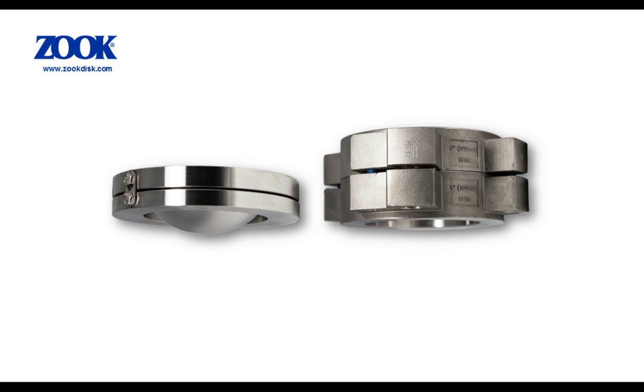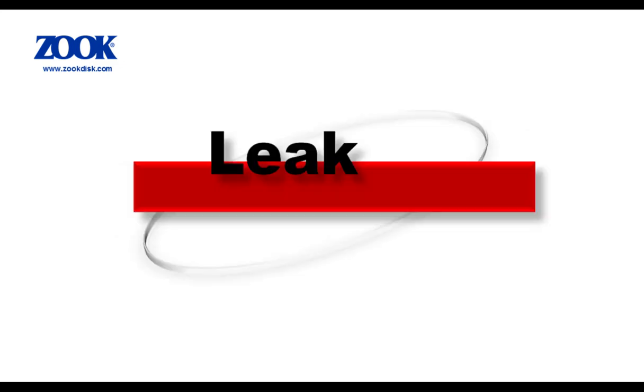What it turned out was that in order to reduce cost, similar to the assembly on the left, the inlet side of the holder had been reduced to a point where the disk dome now protruded beyond. This can pose problems during installation, as it's easy for the disk dome to be impacted during handling or insertion. Sometimes the damage can go undetected. This is exactly what was happening. Our solution shown on the right was simply to provide an assembly with a similar disc style, but with a pre-torque holder that sealed the disc and fully protected the dome. There hasn't been an issue since.